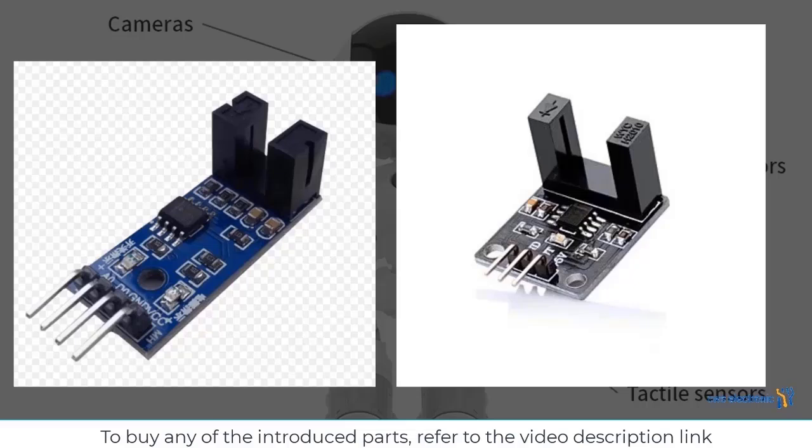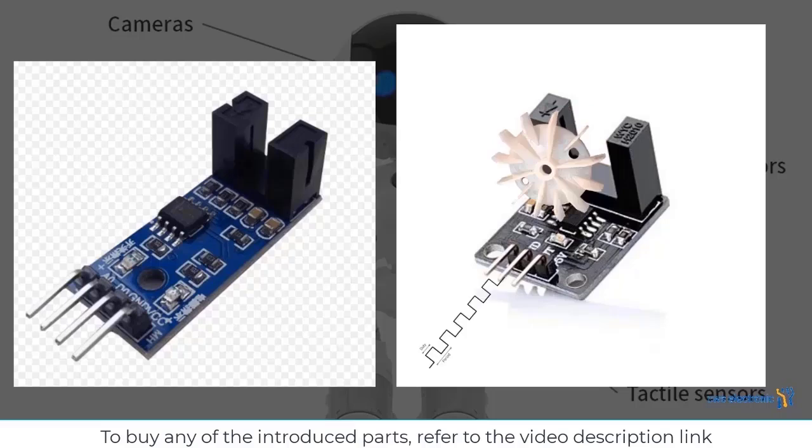So you see that even that sensor is not just for detection and distance, and is also useful for other uses. This motor speed detection sensor works in this way: the infrared transmitter is located in this part and the receiver in this part. Now this sensor is installed on the motor in such a way that a small blade that is connected to the motor rotor rotates between these parts. By rotating, the blade causes the infrared light to continuously disconnect and reconnect, and the motor speed can be detected, meaning that the more disconnections, the higher the speed the motor is rotating at. And the slower the disconnections, the lower the motor speed, and this creates a cycle as an output signal that you will learn well with the programming in the next series.